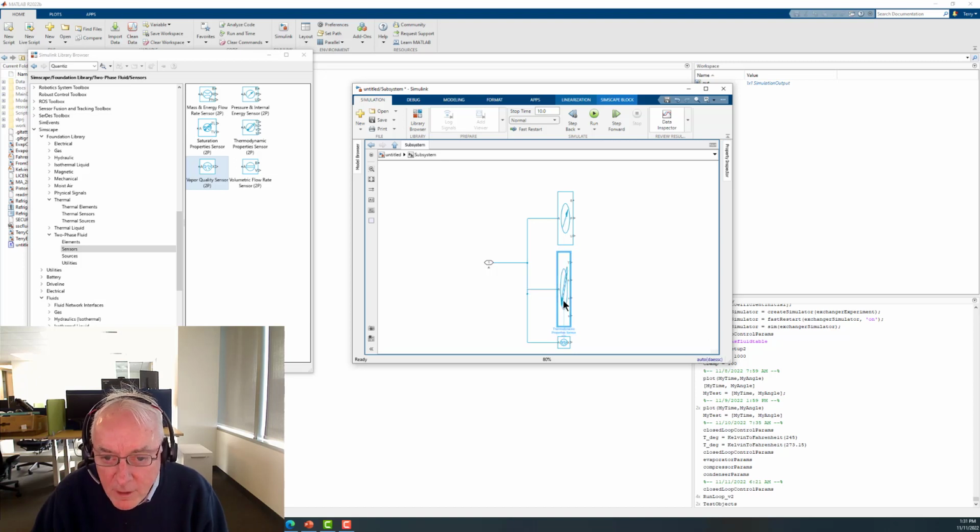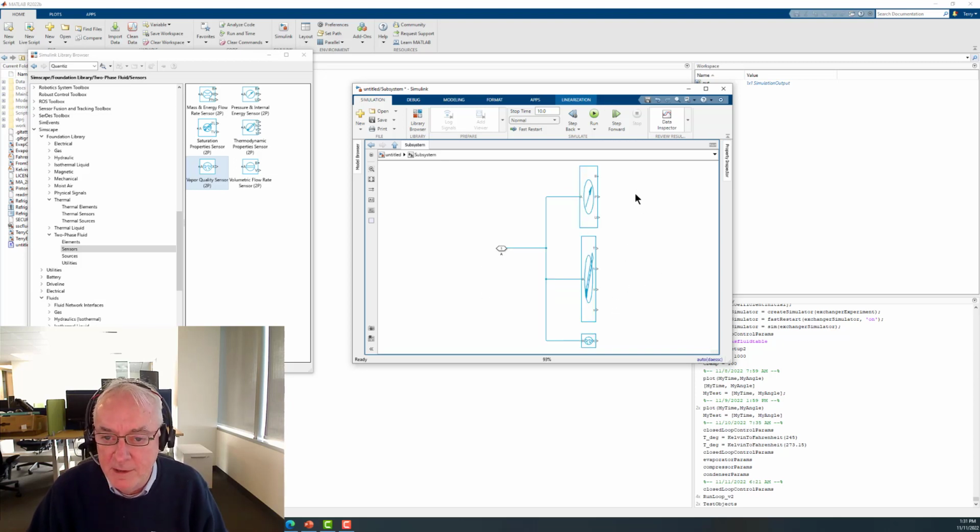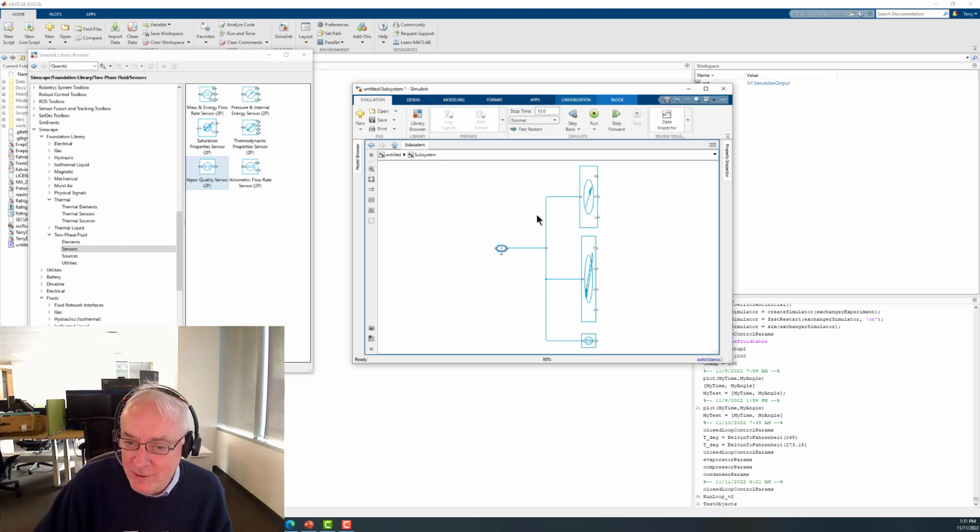Probably good enough. Okay, and we'll contend initially with the thing that everybody contends with regard to Simscape, which is why are those arrows hollow? Why do the lines look different? Why does A not have an arrow on the end of the line? And what we're really dealing with here is connectivity, but we're also dealing with, I'd say, a physical domain environment that lives within Simulink.